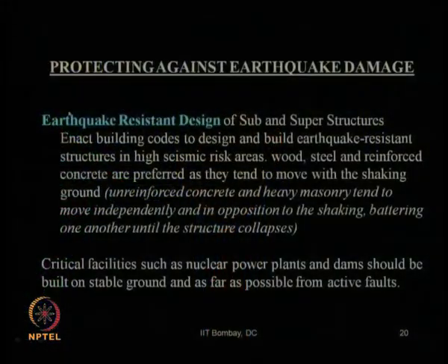The next step for protection against earthquake damage is of course earthquake resistant design and construction, for both substructure, that is underground structures, as well as superstructures or above ground structures. So, enact building codes to design and build earthquake resistant structures in high seismic risk areas. In the first step, you are finding out the seismic risk map, dividing various localities of an area, country, state or city with respect to seismic hazard, vulnerability, exposure, taking all these into consideration.